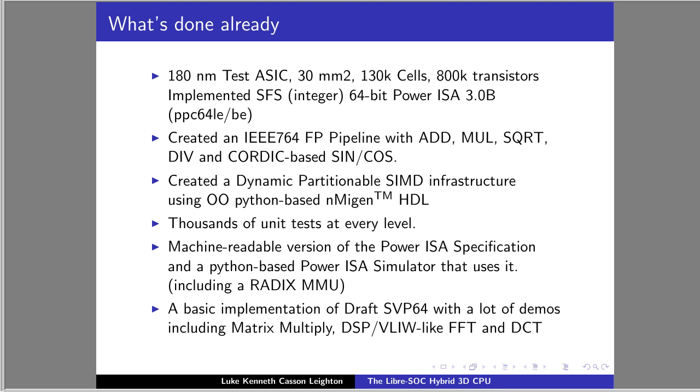They use double the number of registers that the equivalent FFT or discrete Fourier transform does, because of the swapping of the order, where one half of the registers is order-inverted. And this is something that SIMD instructions cannot cope with unless you actually have an inverted-order facility.